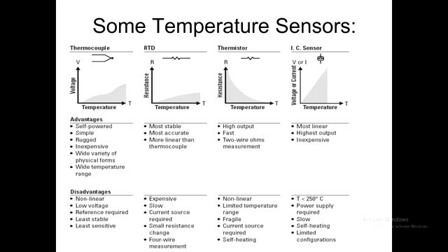There will be various counterclaims about the different sensors about how much thermal mass they have, and therefore how much using them will affect the measurement. It really depends on the housing. The very smallest one would be the thermocouple, because in essence it's simply 2 wires joined together. I'll explain that, if not today then in another session.